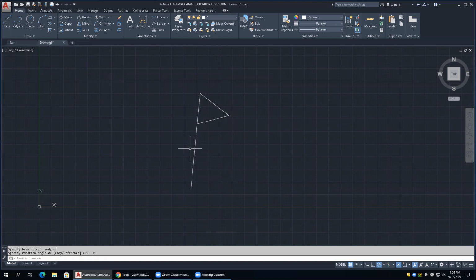I don't know what that is, and I couldn't even figure it out that easily. But what I can do is reference that shaft on that flag, and AutoCAD can calculate that for you. So that's called a reference option, okay? But we need to be very precise, so that's where we have to use those O snaps, okay?